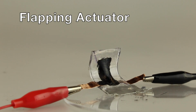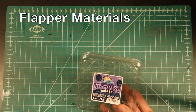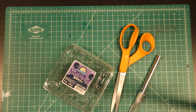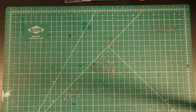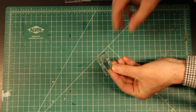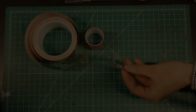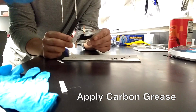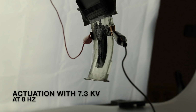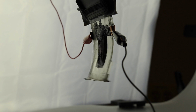Now, let's make some flapping actuators. These are the materials you need for the flapper: thin plastic, tools for cutting, thicker plastic for the frame, super glue to glue the plastics together, VHB tape, and copper tape. Assembly is the same as with the previous actuator. Apply grease to both sides. When high voltage is applied, the actuator flaps. It creates sound at higher frequencies.